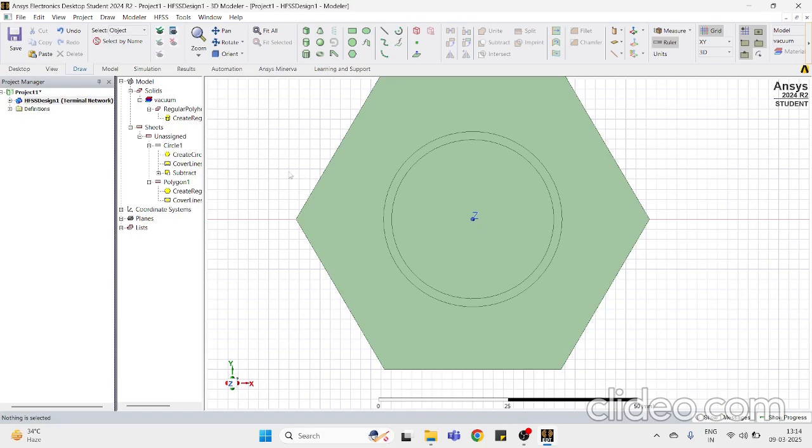Yep. So after the ring, a little bit of a tricky part, I would say, is to draw those feed lines. So it's very intuitive, to be honest, because the width of these feed lines is 3 mm. We know that, and the length of this, starting from here and ending here, is approximately 14 mm, which is known to us.